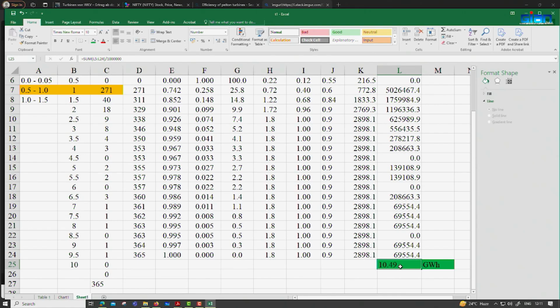But if the total package price the manufacturer gives you for the Francis is considerably lower than the Pelton, then you can still consider it. That all depends upon your cash flow calculation, your economic evaluation. So, you must do one cash flow evaluation with a Pelton turbine and another cash flow analysis with a Francis turbine, and maybe Turgo was also possible. Another cash flow analysis is for Turgo.